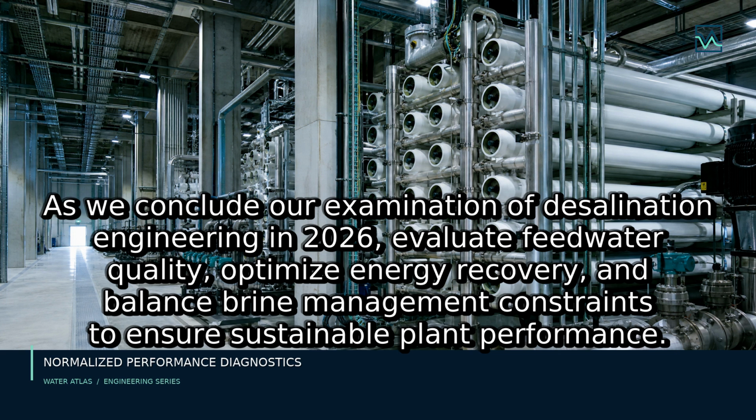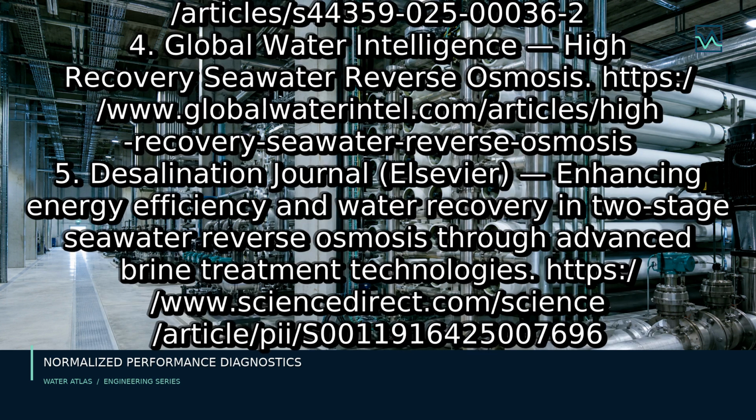Energy has historically been the primary operational cost driver in seawater desalination. Without energy recovery, passing seawater through reverse osmosis at 70 bar would consume prohibitive electrical power. Fortunately, modern desalination engineering has been revolutionized by advanced energy recovery devices, specifically isobaric pressure exchangers that transfer up to 95% of hydraulic pressure directly without mechanical conversion. Through optimized integration of isobaric ERDs, state-of-the-art SWRO plants operating in 2026 have pushed specific energy consumption down to less than 2.5 kilowatt-hours per cubic meter.